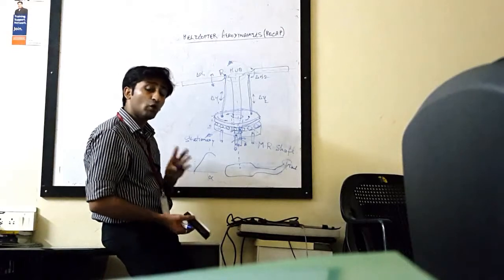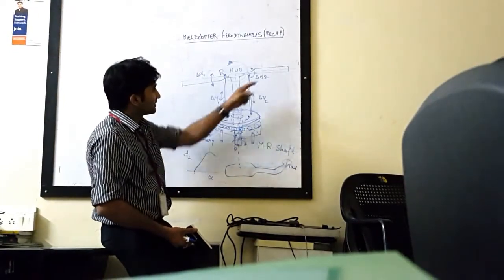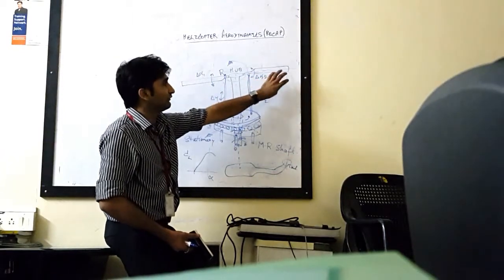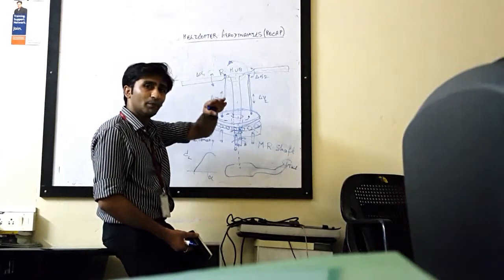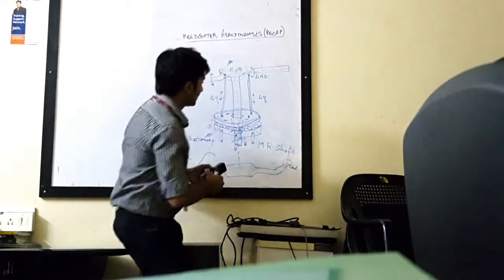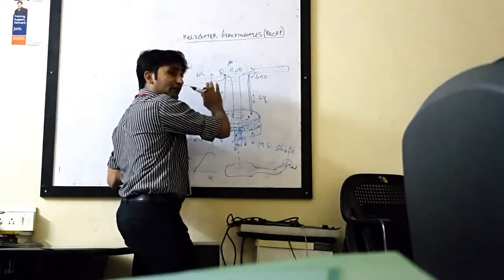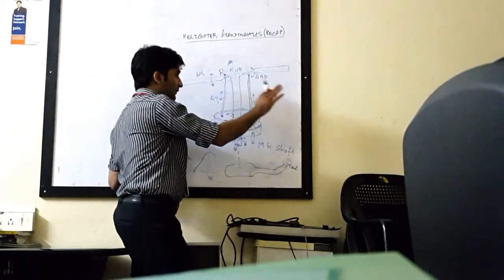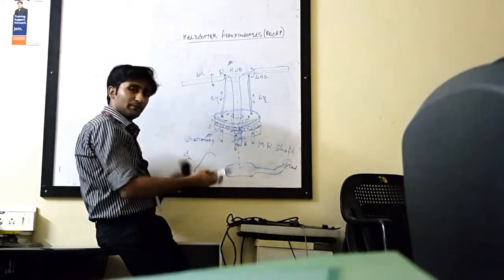Now in terms of forward flight, what happens is the CL here, or the total lift here, will be greater than here. So you need to pitch up momentarily. So you will pitch up. So what happens is, when the CL is greater, when the total lift is greater, whenever the rotors come towards the rear or come towards the azimuth of phi equals 0, then the lift will be maximum.